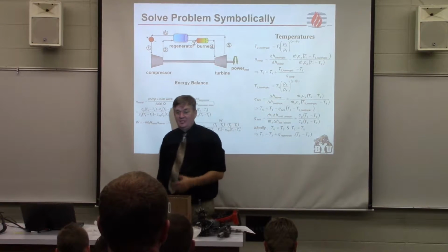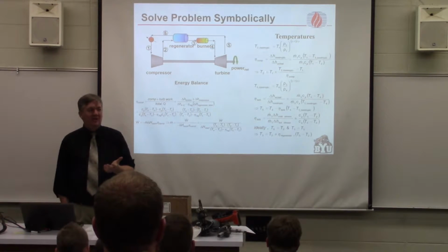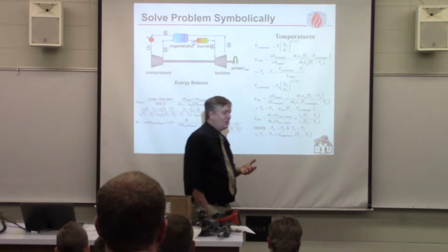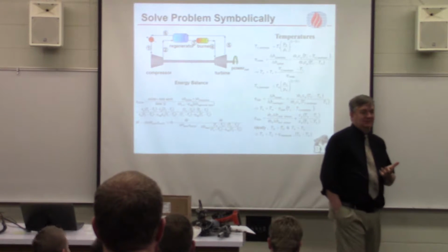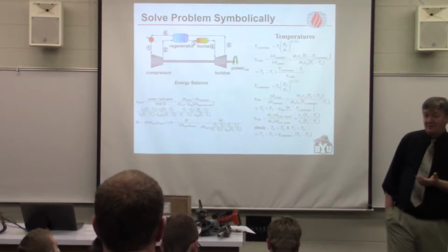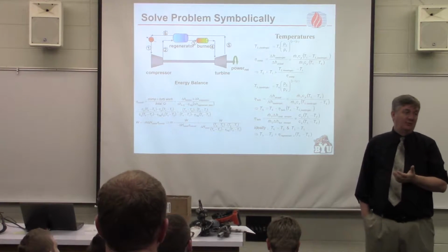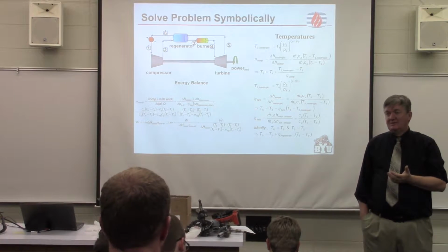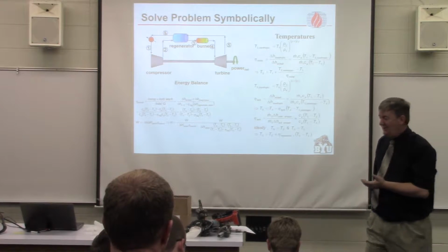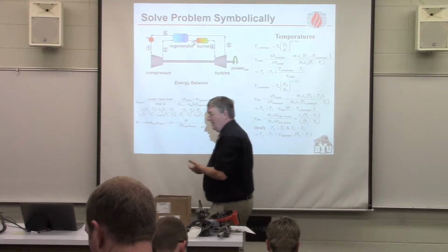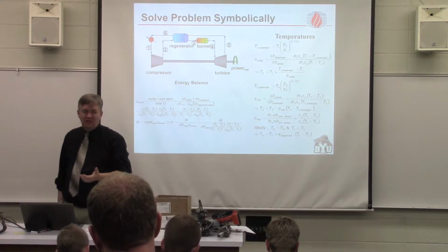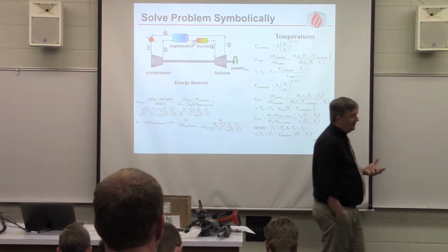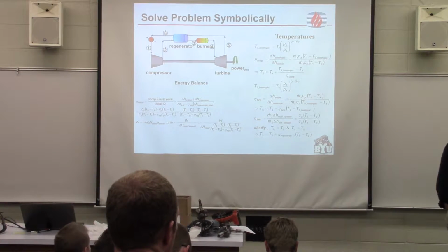the compressor efficiency. And compressor efficiencies, by the way, anybody know what a world-class natural gas compressor efficiency should be? Are compressor efficiencies higher or lower than, for example, liquid pump efficiencies? Lower, all right, because gases are harder to compress. Off-the-shelf, routine, relatively modestly engineered compressors have efficiencies in the 70% range.